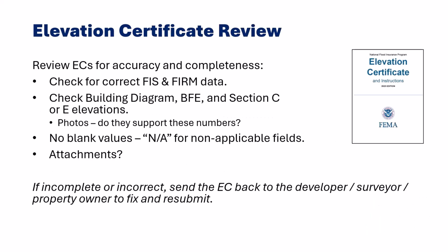When requiring elevation certificates as part of the permitting process, don't just simply accept and file one because a surveyor stamped it and gave it to you. You should always review ECs for accuracy and completeness. You want to check that the information supports your community's official determination of compliance. If the form is incomplete or incorrect, send the elevation certificate back to the developer, surveyor, or property owner to fix and resubmit the form.